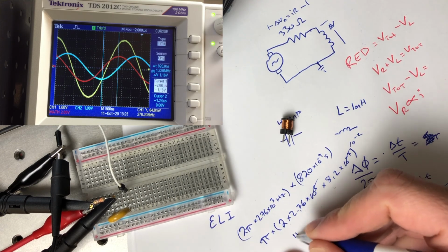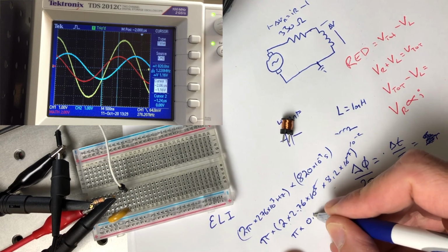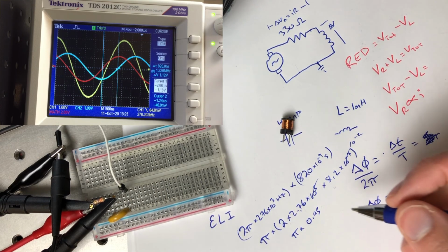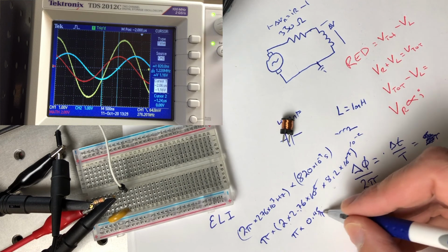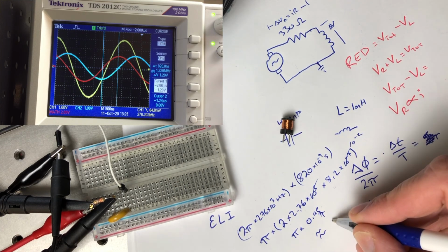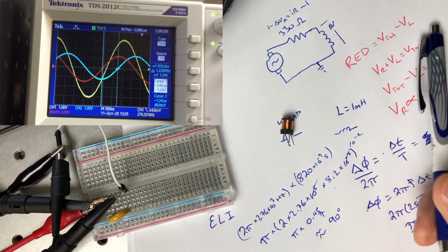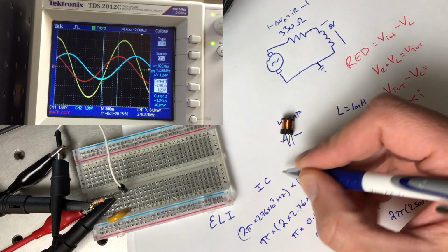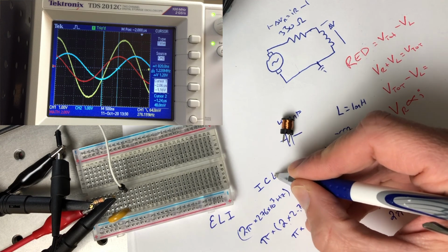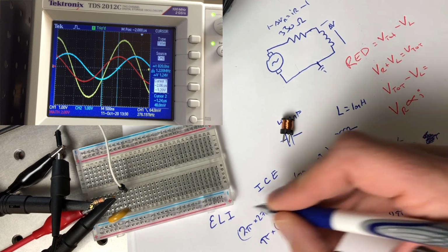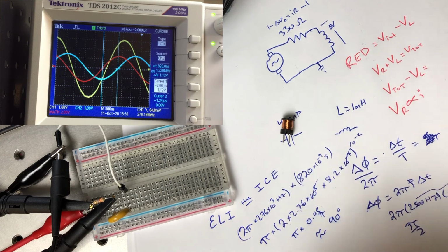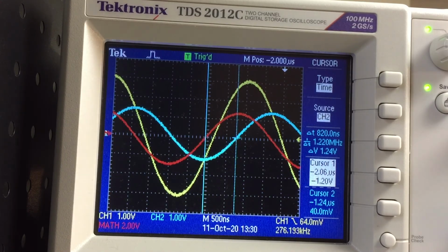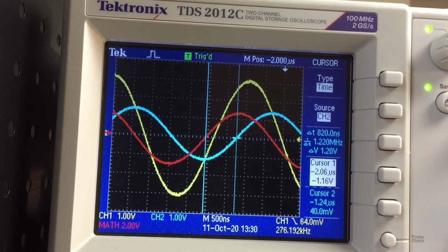So pi times 0.45. And we've rounded down a few things. It was 2.76 something. That last significant figure here. This is pretty much our 90 degrees. But now it's a 90 degree phase shift where the current is leading the voltage, or the EMF, in this Eli the Iceman nomenclature. Anyway, let's look at the scaling of the current as a function of frequency.